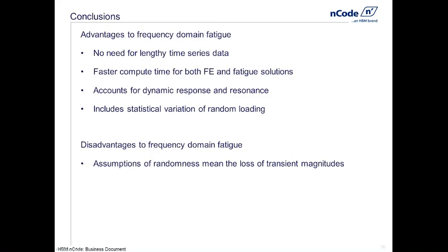So in other words, if I were to look at wind gusts over a long time period and look at the average, well, that's not quite as big as some of the cycles were. If I look at the peak hold, that says that we always had the worst case wind gusts constantly. So we're stuck in this kind of no engineer's land between two assumptions: stationary with averaging results in stress cycles that are too small, and peak hold results in stress cycles that are worst case and too big. So that can be a real challenge.